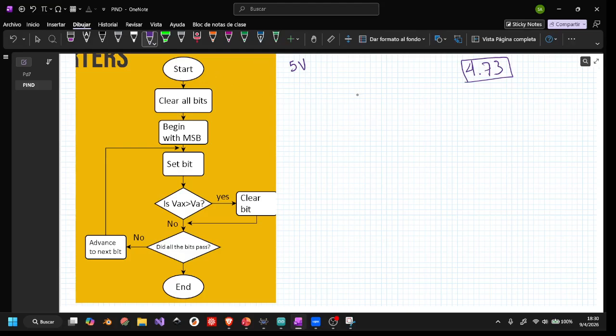The ADC in the Arduino Uno is 10 bits. It means we can count up to what number with 10 bits? Yeah. 8 was 255, right? So 9 should be 512. And 10 it's 1024, right? So we can count from 0 up to 1023, okay? Because we have 10 bits. That's 2 to the 10 equals to 1024, right? Okay, including the 0, we have to subtract 1.